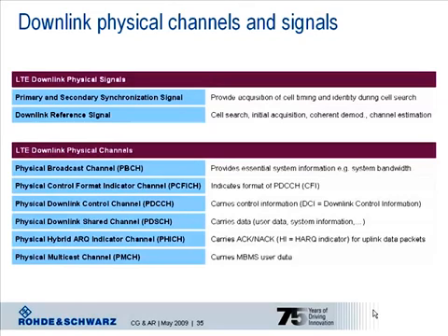Further, LTE uses physical channels which carry information data from higher layers, layer 2 and layer 3. These are, for example, the physical broadcast channel, carrying essential system information, and several control channels, such as the physical control format indicator channel and the physical downlink control channel, which are required to inform the UE about scheduling decisions. The physical downlink shared channel is used to transport any kind of data: the obvious transport of user data to the device, but also system information or paging information.